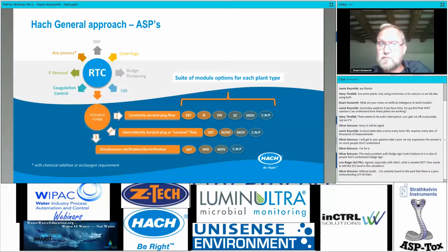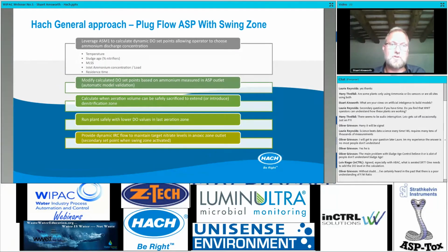We've also got most open valves. That allows us, again, an off-the-shelf solution to optimize the aeration system. That's too big a topic for the slot that we've got today. And I've put nutrient addition as well. So if you've got an activated sludge plant which is nutrient limited, we've got automatic methods to make sure that the N and P availability is optimal to make sure that you achieve full treatment. So this is where swing zone fits into our whole suite of offerings.